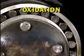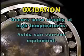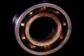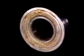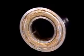Oxidation occurs when a lubricant combines with oxygen, and it tends to occur more rapidly in equipment that operates at high temperatures. The acids produced by oxidation can corrode equipment and lead to lubricant leakage. Besides forming acids, lubricant oxidation can form harmful deposits on metal surfaces. The varnish deposits on this bearing came from oxidized grease.